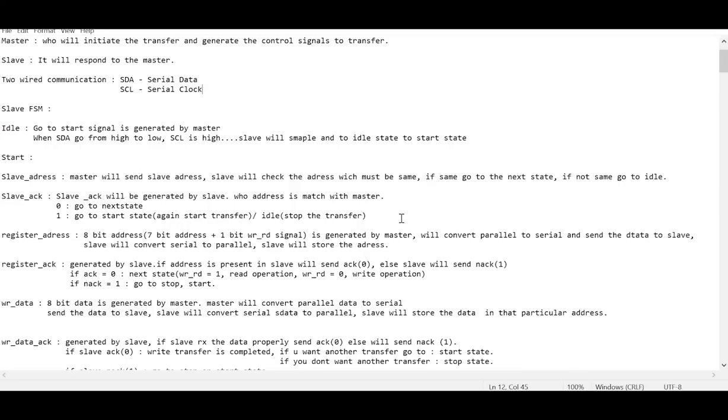There is a frame format, right? What is there in the frame format? There is an SDA signal, an SCL signal, data, and a clock. There is a start condition for the data. What is the start condition? Can anyone tell? High to low for SDA, and for the clock it should be constantly high. So this is the start condition.